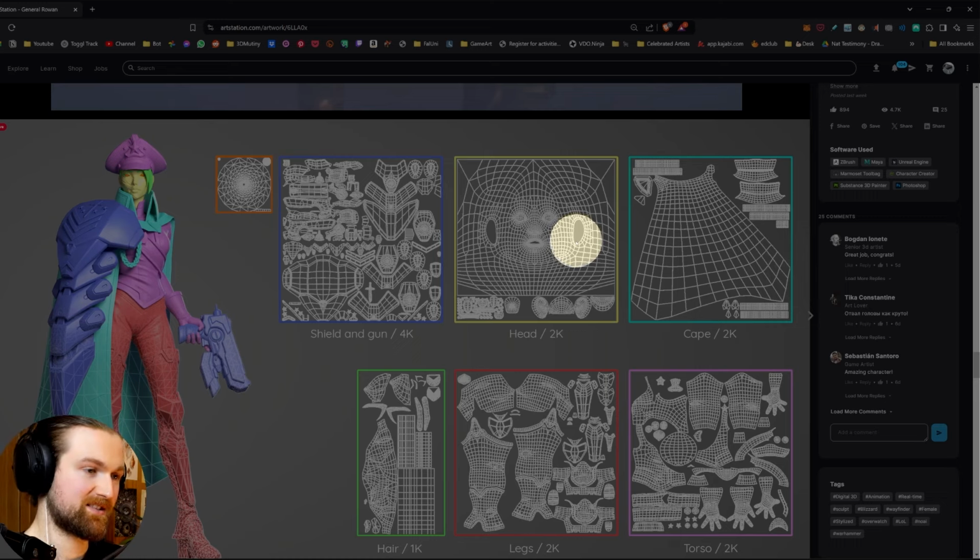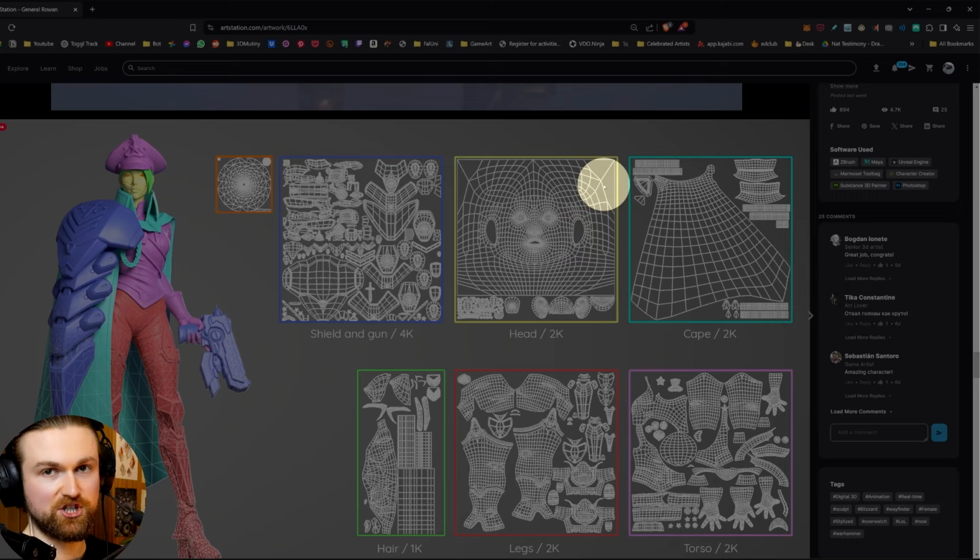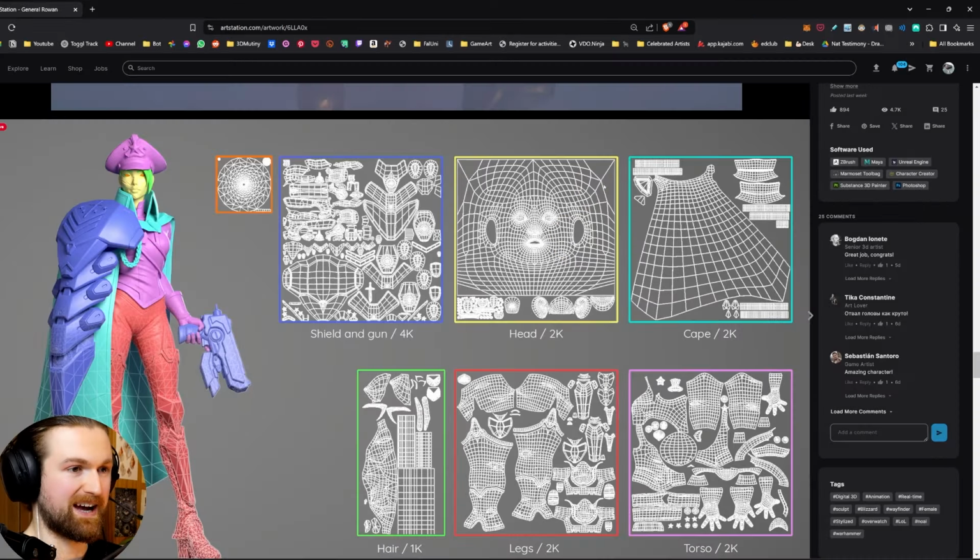And potentially something might happen in the future, whether it's a design change or art feedback, where we might need that UV space. So say, for example, an earring or an extra tooth, or all these little things we need to have available just in case, some extra space. So with the head, try and favor non-deformation and leave empty space.